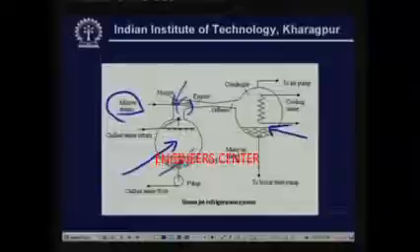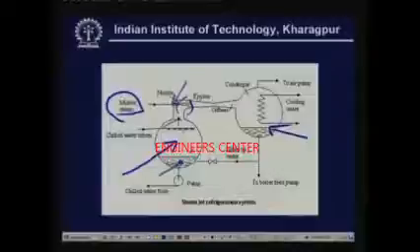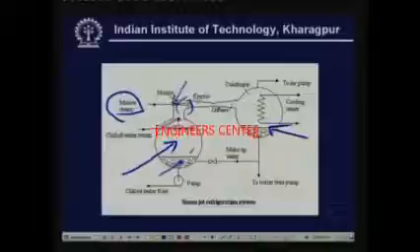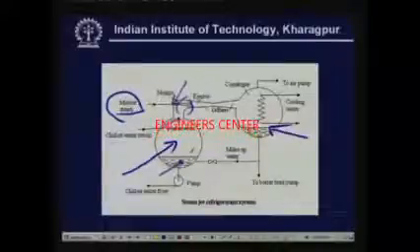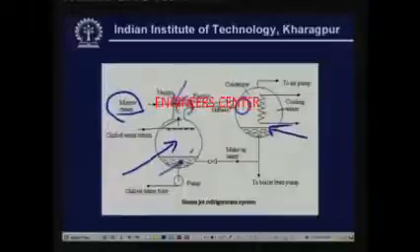Okay. Now what happens to this vapor? This motive steam plus the vapor that is evaporating in the evaporator both get mixed and then they flow through a diffuser. In the diffuser, what happens is you convert the kinetic energy back to pressure. That means at the end of the diffuser you again have a high pressure steam. Okay. This high pressure steam now comes in contact with the cooling water that is flowing through this heat exchanger.